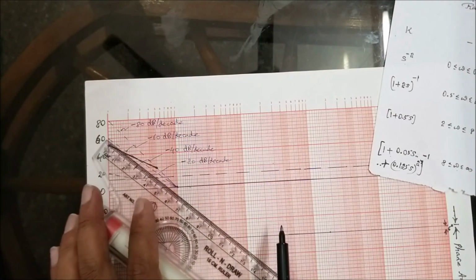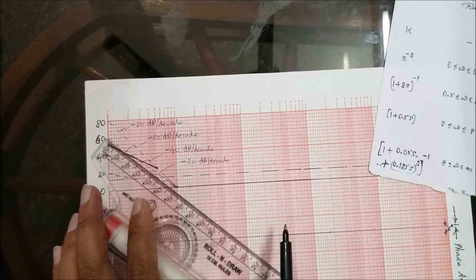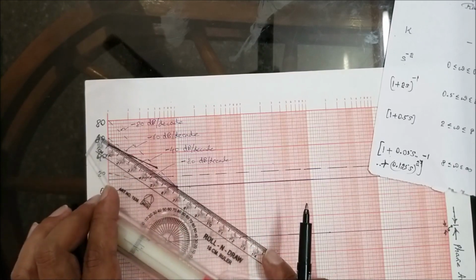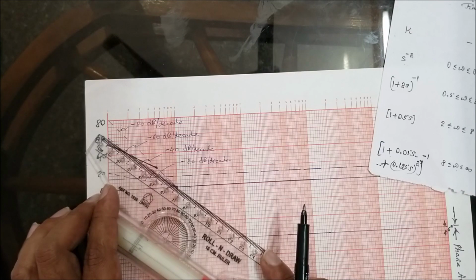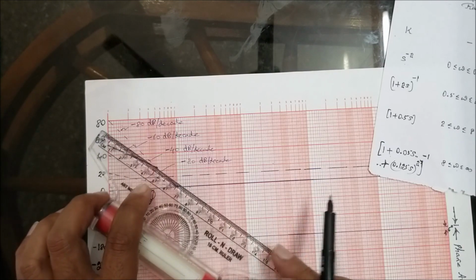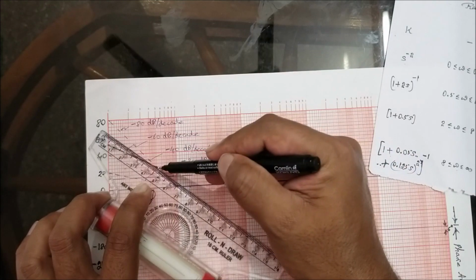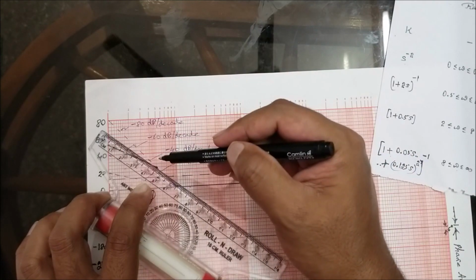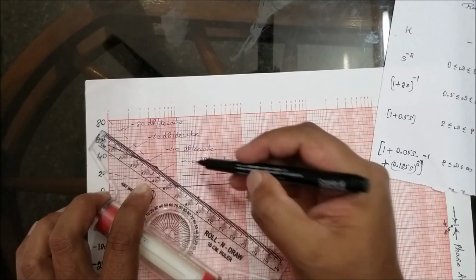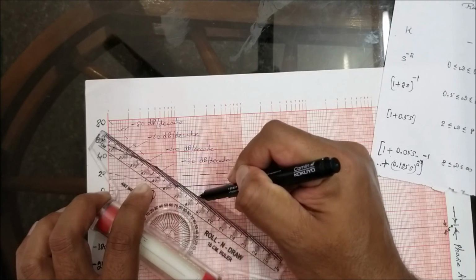Now you complete the magnitude plot. Take a line parallel to minus 60 decibels per decade. So this is the minus 60 decibels per decade line, for which I will take a parallel line from 0.5, that is the end of minus 40. From 0.5 I should draw till 2. This is 1, this is 2. So till here, correct, draw.